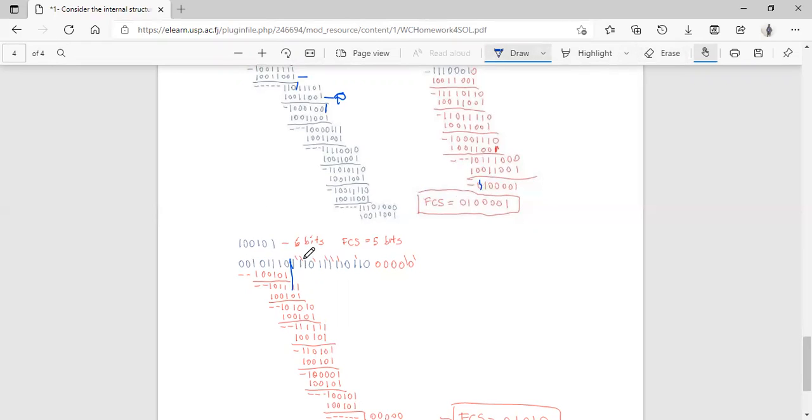Mistake, excuse me for that. Let's say till this one we are carrying these 2 down. Now we can perform the XOR with this particular polynomial. Again, we write the polynomial starting from the first 1 that we have. The first one we have is this one. We have ignored these 2 zeros over here. So 1 is over here, so straight underneath, we start writing our polynomial 1, 0, 0, 1, 0, 1.